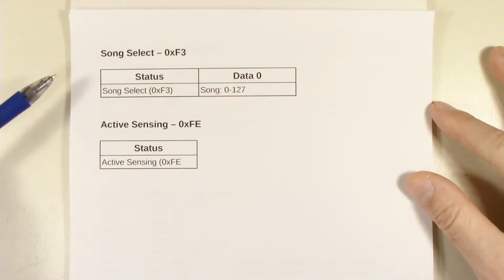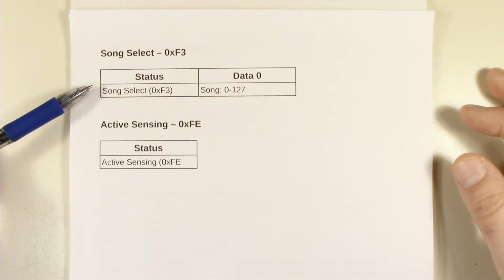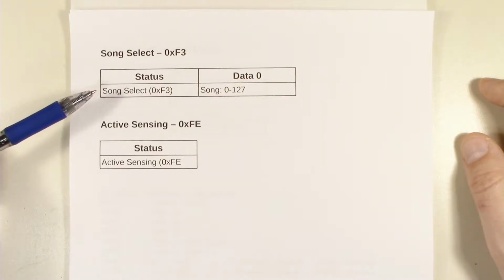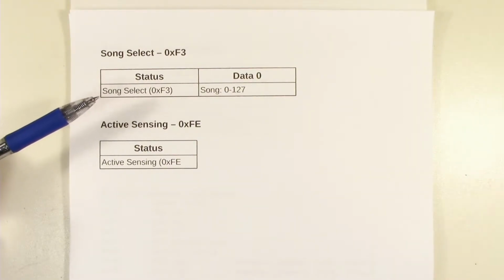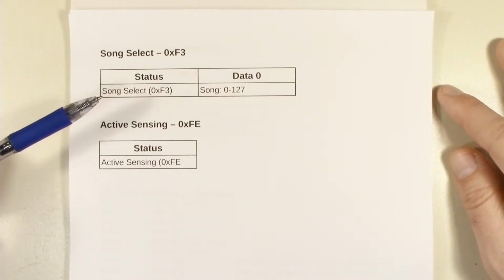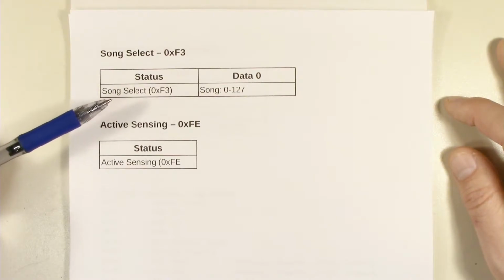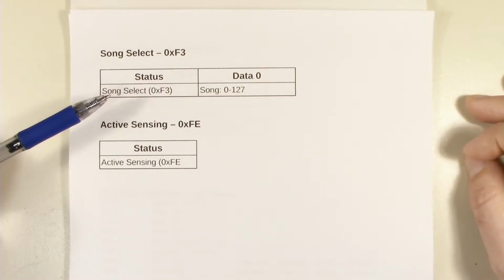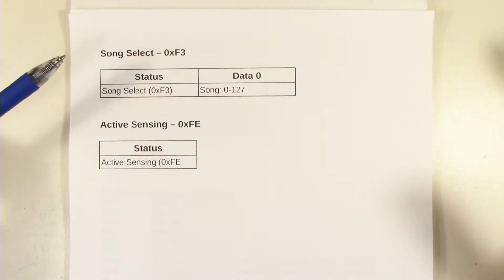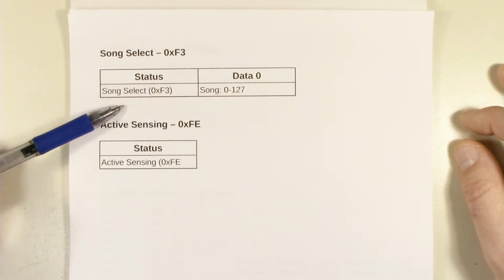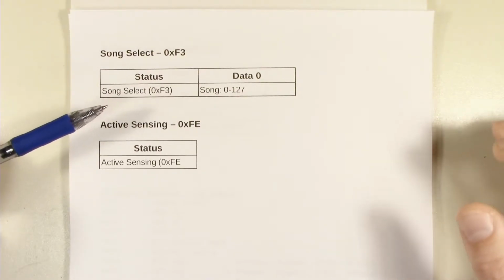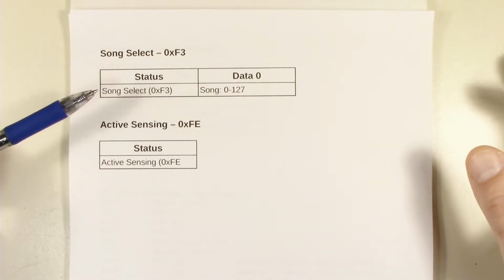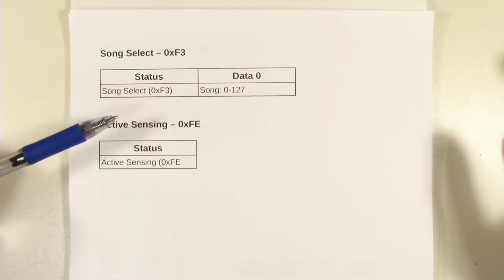Now, let's say you're implementing a system that does this, and you send a song select message. You can't just assume that the other device will immediately be ready to go, because even in modern systems, the file system has to load data off a disk, and those kinds of operations aren't immediate. Even on the latest flash-based things, there's still time taken for the file system to find the file, open it, read in the data, and figure out if it's correct. So when you send the song select message, you should wait. I forget exactly the amount of time the MIDI spec gives, but there's an amount of time you should expect it will take before the sequencer on the other end is ready to go.